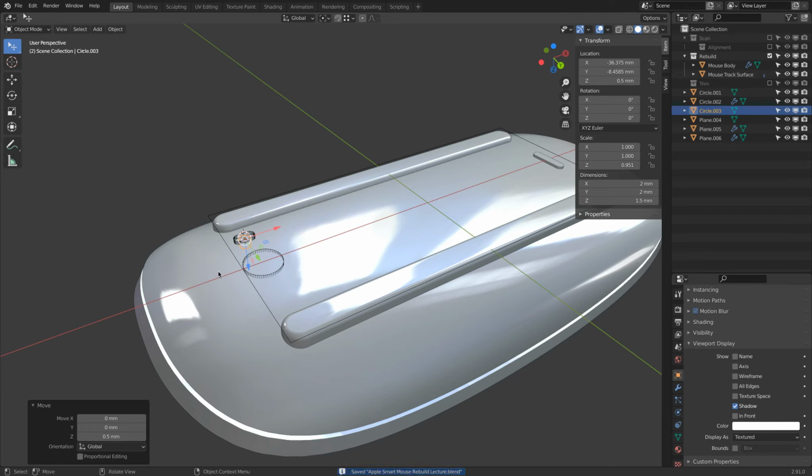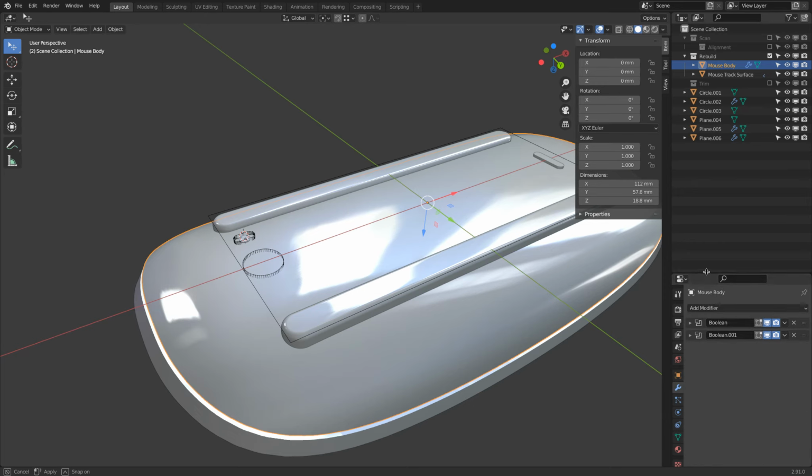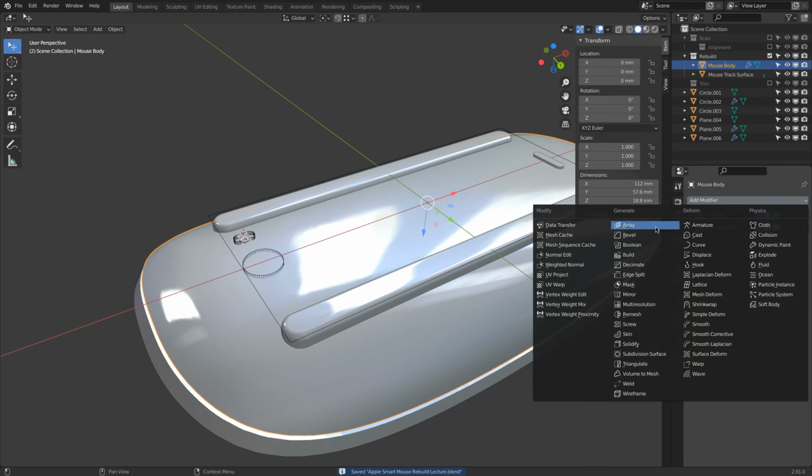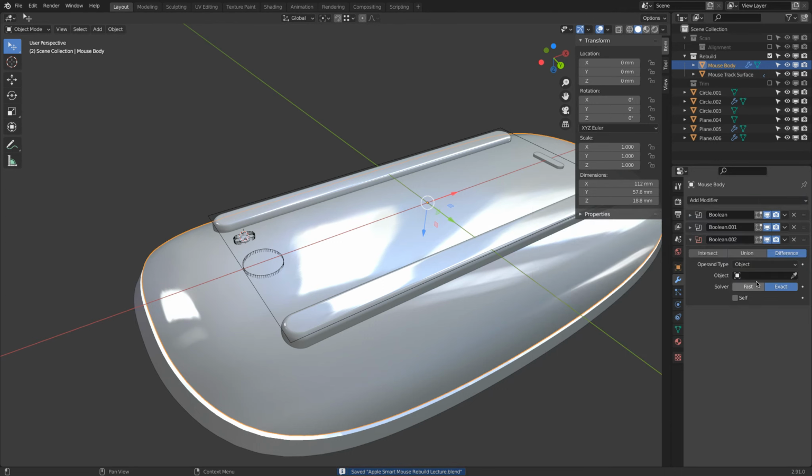What we can do now is we will select this, go to modifier, drag this up, Control S to save, add bevel modifier, set a collection. Then here we will make a new collection. We will call this bottom interface.